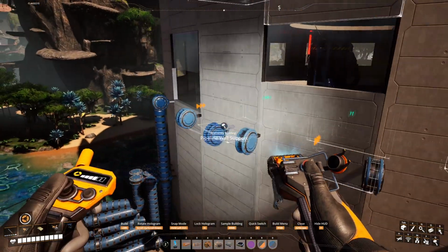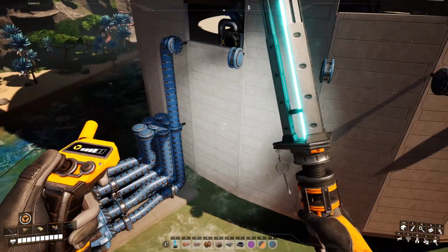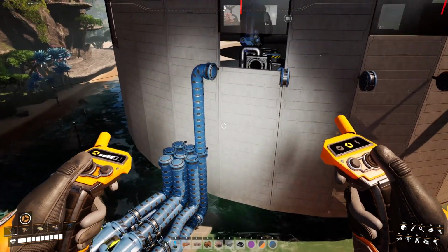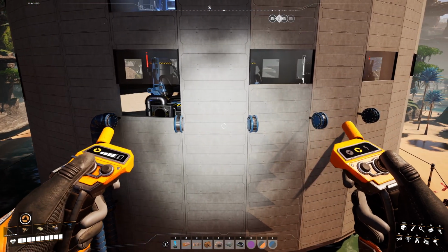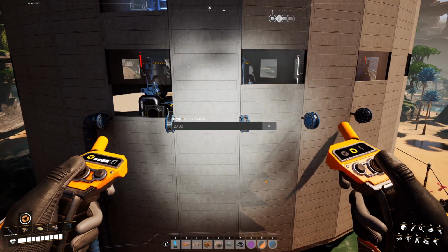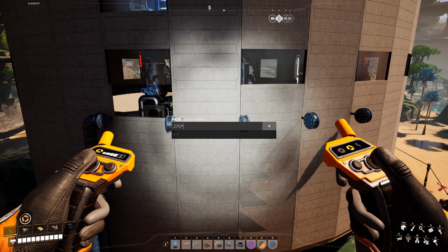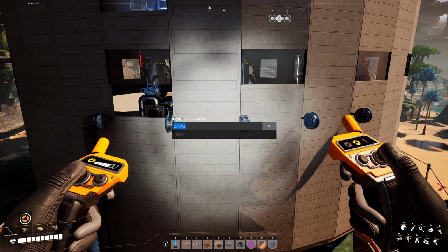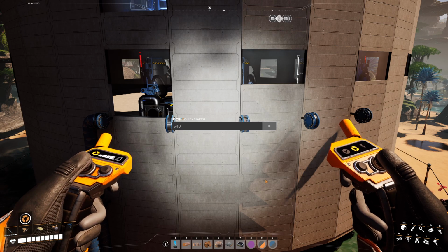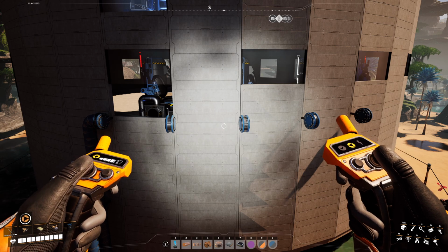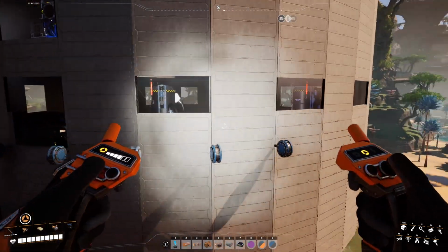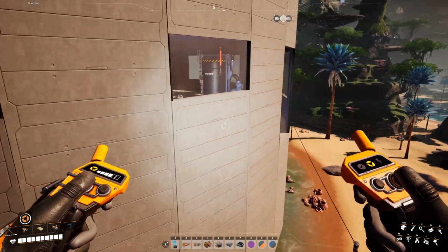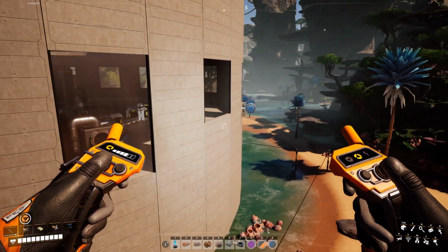So this one, because we've got one pipe coming up here, we're doing 270 times 2, so our 270 per pump times 2 is going to give us 540, and every machine needs 90. So if you do this, you can see, okay, we need to cover 6 machines. So 1, 2, 3, 4, 5, 6. So we need to go all the way to there.